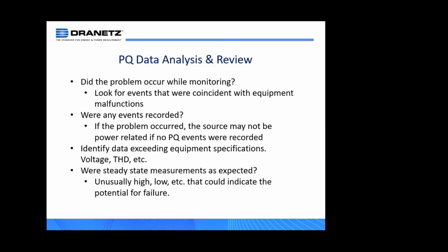Absolutely not. When you're approaching solving power quality problems, it's all about troubleshooting, and troubleshooting is always eliminating all the factors that may be causing the problem. So if you've connected the instrument for a week and it hasn't recorded any events, then the problem that might be occurring is not power related. Too many times the power gets blamed because you don't have monitoring in place. People say, no, it's not the equipment, it must be the power. I hear that statement all the time.